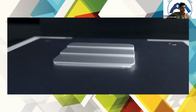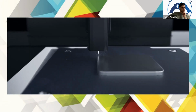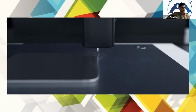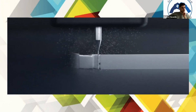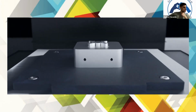After a number of layers are printed, high-speed cutting tools automatically refine the shape and surface finish of the printed layers. Because the dried FMP material is not yet fused, the shape refinement process is up to 50 times faster than conventional solid metal cutting. The steps are repeated to build and precision finish the entire part.